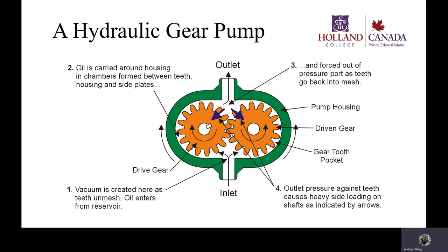They work very simply on vacuum coming into the inlet on the bottom of the pump here. Because the pressure on the inlet side is lower than the outlet side, obviously, and the inlet side pressure is actually lower than the vented pressure of the reservoir. Most of these gear pumps are used in systems that do have a vent on the reservoir.